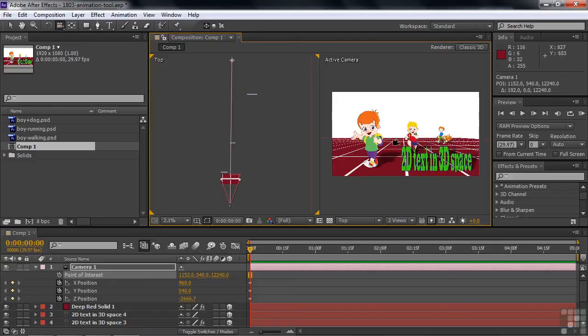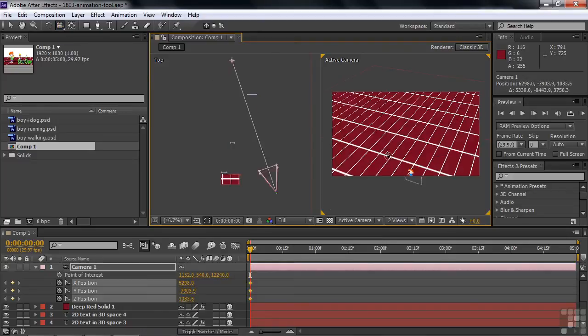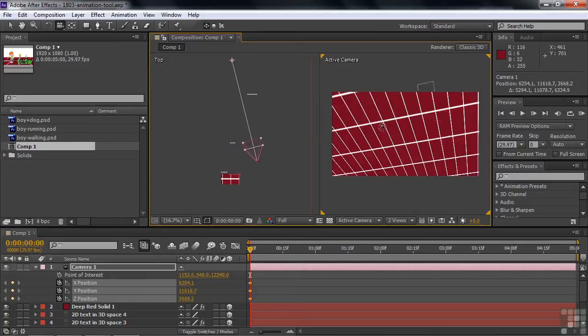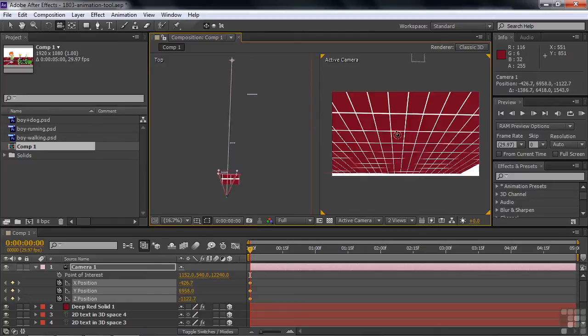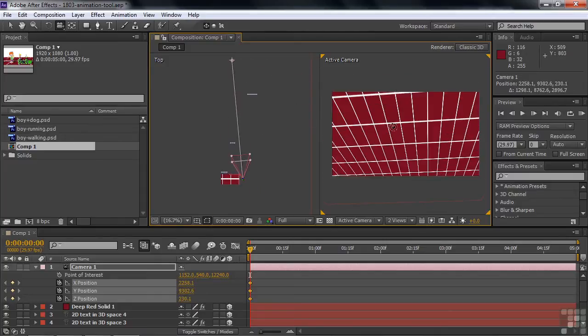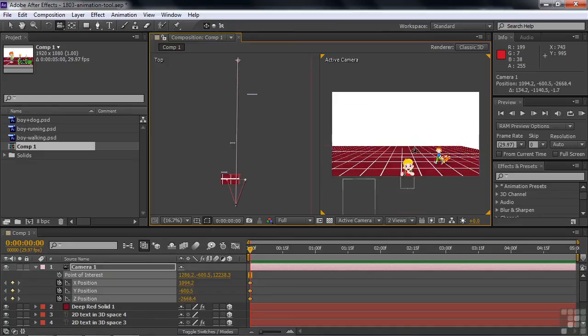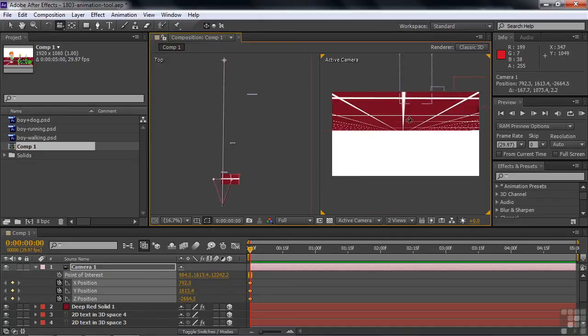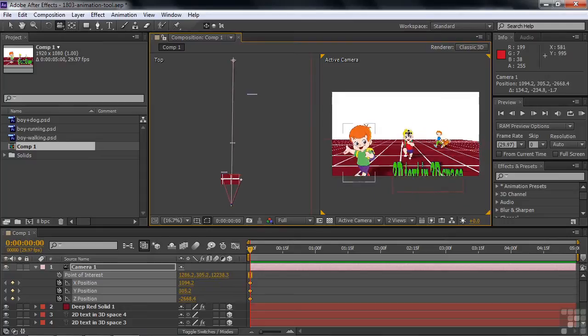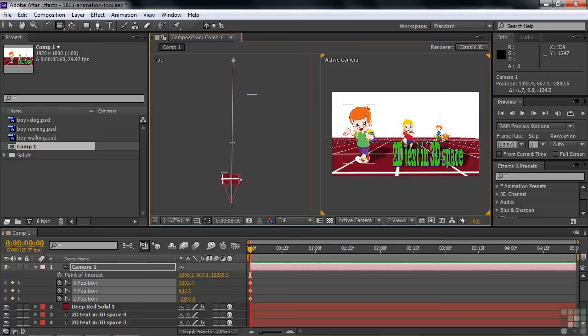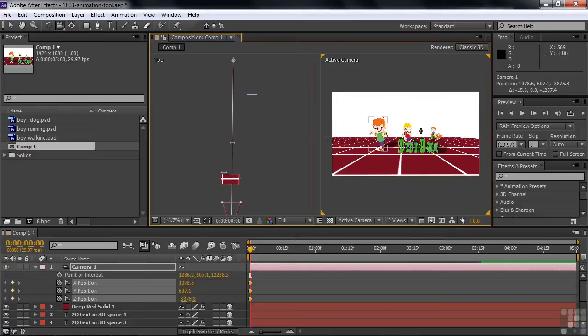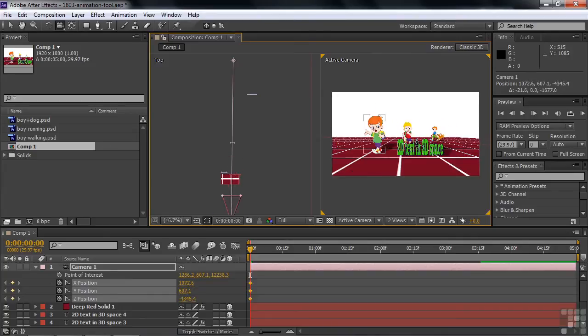The left button is the Orbit tool. It lets you orbit around like this, change all kinds of things. It's really quite amazing. Watch out, it's pretty wild. So you have to be kind of careful how you do this. I'll do Control or Command Z to undo that. The scroll wheel, or the middle button, click that down, and you get the XY plane, the plane that we see in front of us. You get to move that around. Literally, you drag it in the direction that you want it to go, like that. And the right mouse button is the Z track, in or out, like that. Out and then in, like so.